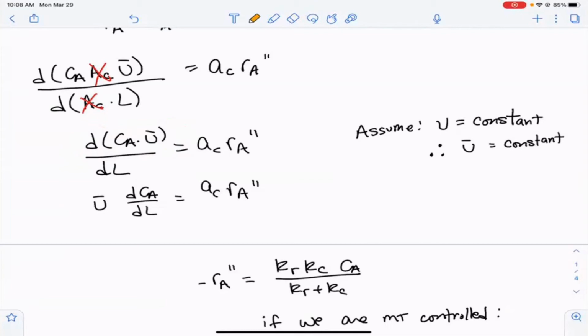And you would end up having the functional form for the volumetric flow rate in here also, before you would convert it into the cross-sectional area, because you know how it changes with a constant cross-sectional area. We know the form: V equals V0 times (1 plus epsilon x) times T over T0 times P0 over P. I think this is right, but sometimes I flip these by mistake.